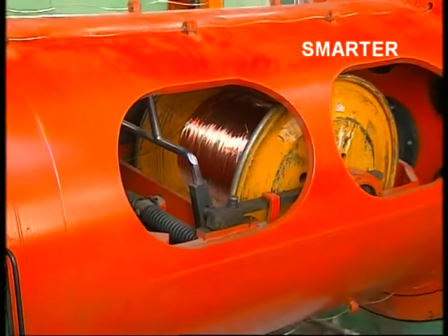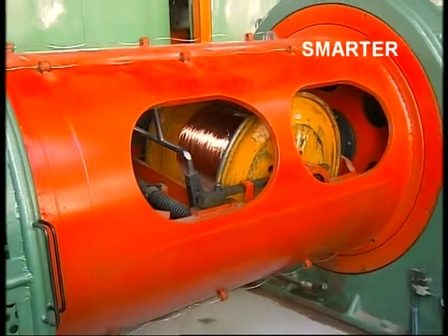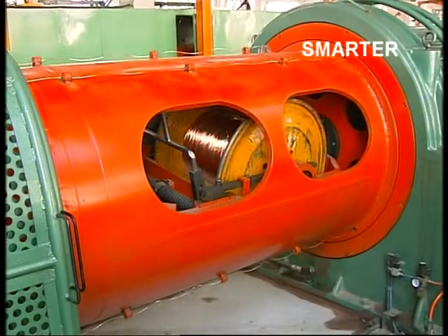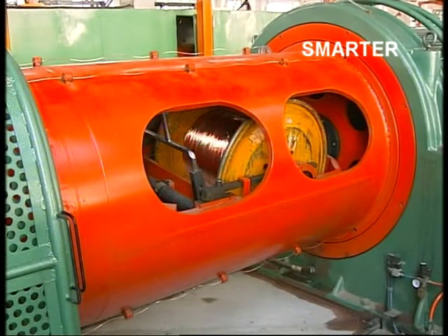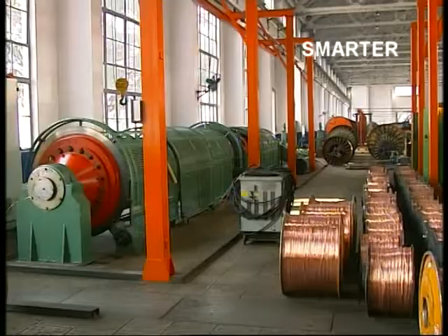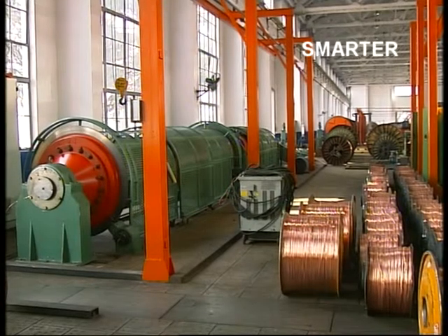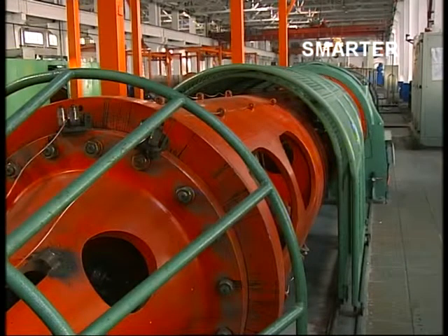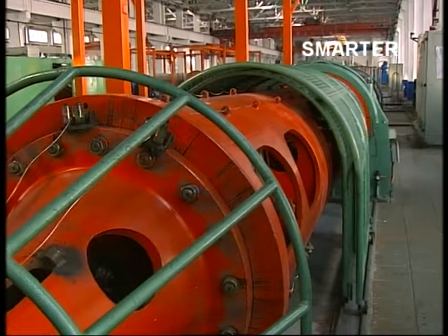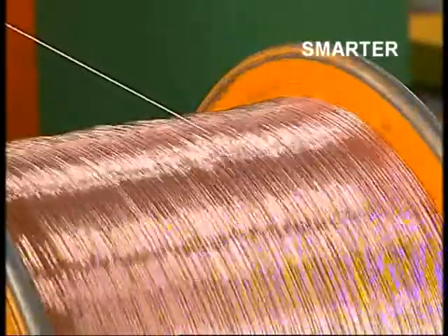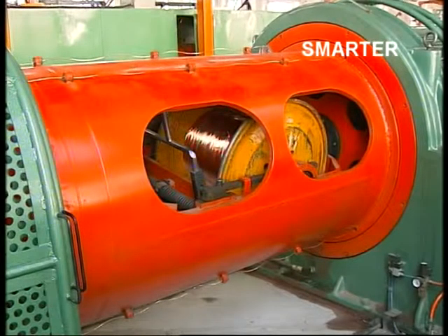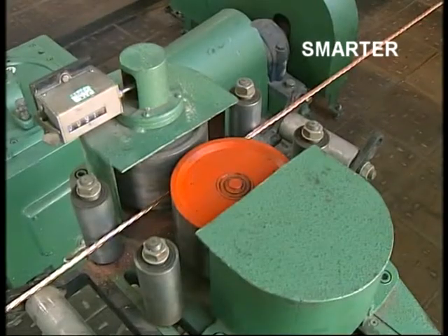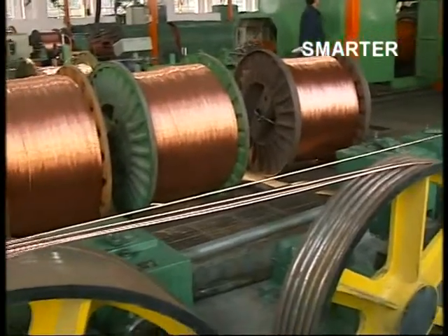JGG 630 1+6 tubular stranding machine was designed and developed by our company in 1999. This kind of machine is mainly used for copper wire, aluminum wire, and steel wire stranding, with features of high speed and efficiency. The JGG 630 1+6 tubular stranding machine consists of a central payoff, wire guiding stand, cage, assembly die holder, meter counter, capstan, and take-up.